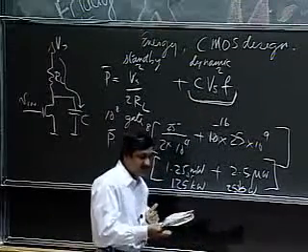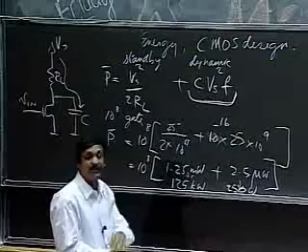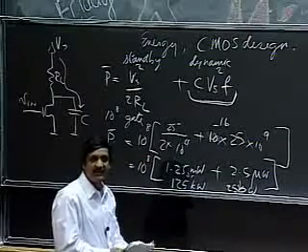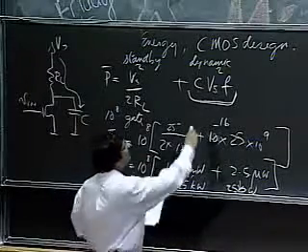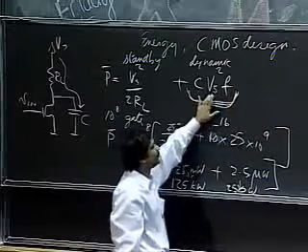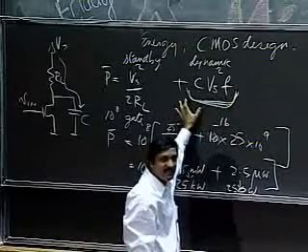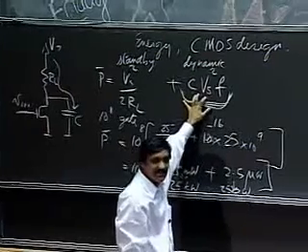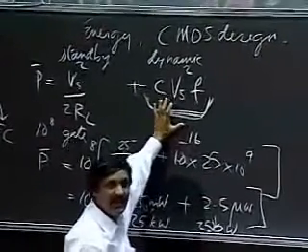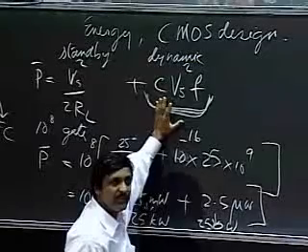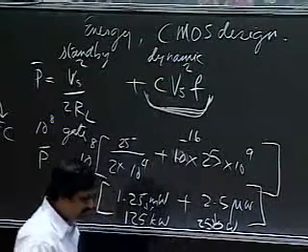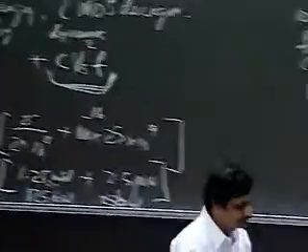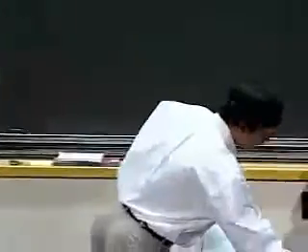It also says power supply voltage in the range of 0.7 to 1.3, right next to the power expression. So you can see why they tell you all of that, because the voltage, the frequency and the number of gates all come into the power equation. This really simple expression here, it's amazing how close this is to what people use for the dynamic power in chips.